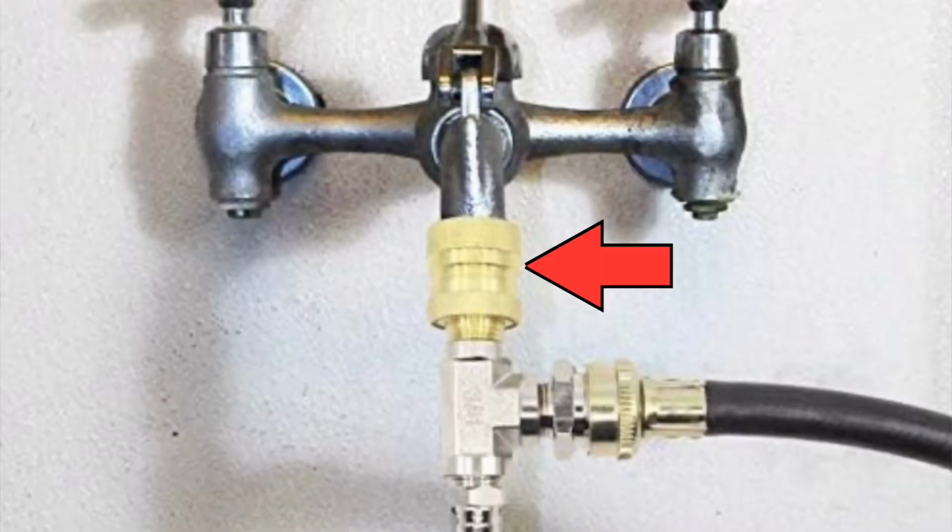One of the things that you want to avoid in the restaurant, and you may have noticed this, and one of the reasons why you need an air gap is something called cross-connection. A cross-connection is a physical link between dirty water and safe water. The reason why is there is a risk for something called backflow, where the dirty water might siphon up into the clean water. A lot of you have probably seen something that looks like this or like this. This is backflow prevention, and these are actually required, especially in restaurant settings.